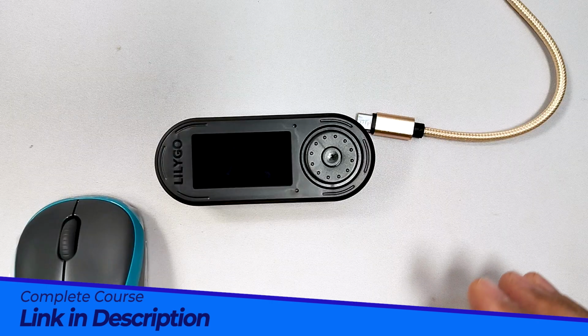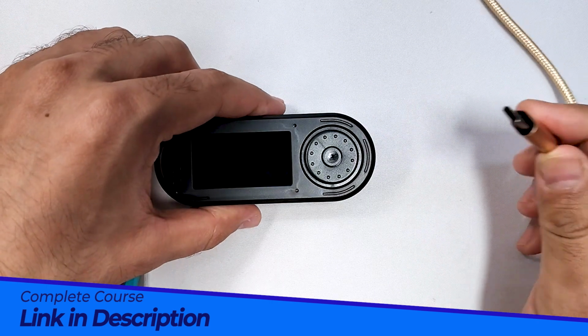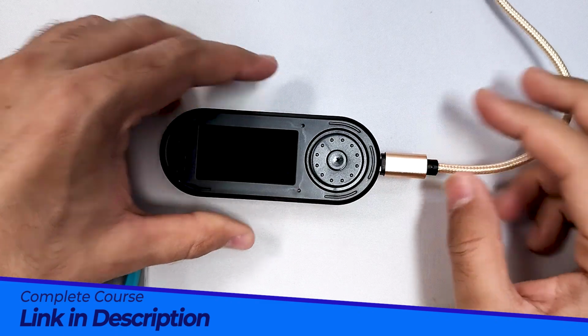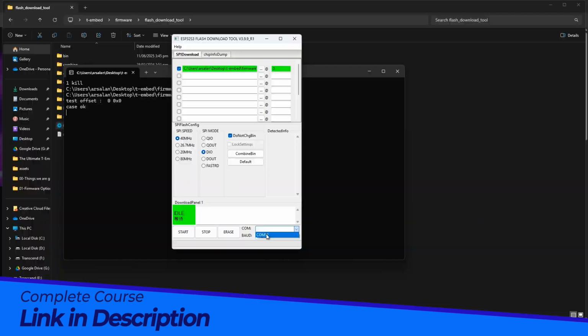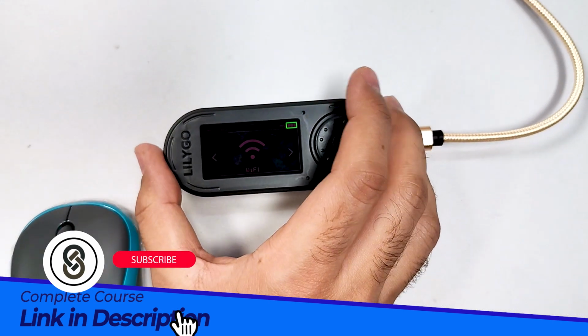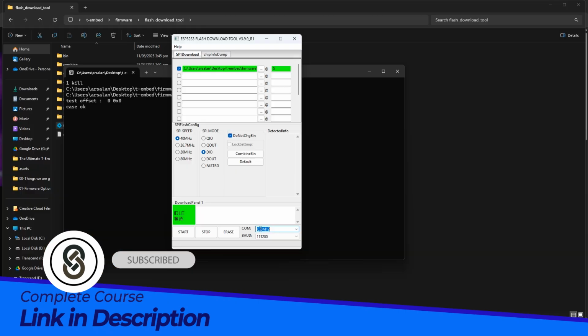Now what we have to do is just connect our device without holding any button. We just have to connect our device, doing nothing. Over here you can see COM port 12. You have to make sure your device is turned on. Over here you can see my device is turned on, and over here you can see the port. It might be different on your system. So we have to select this port. This is all we have to do, and we can just start flashing our firmware. So let's just start.